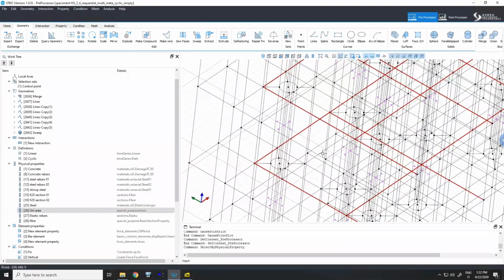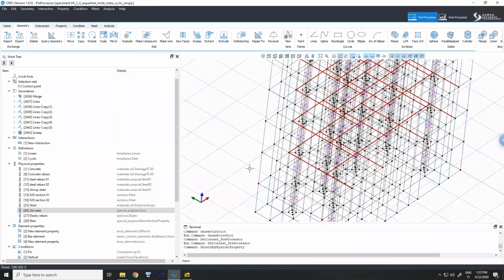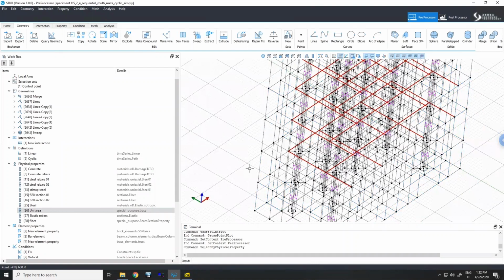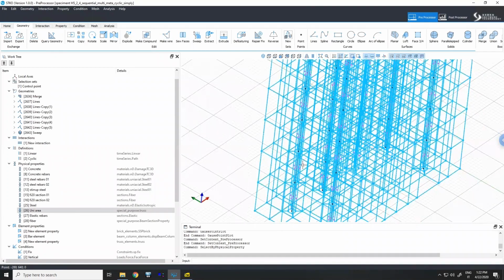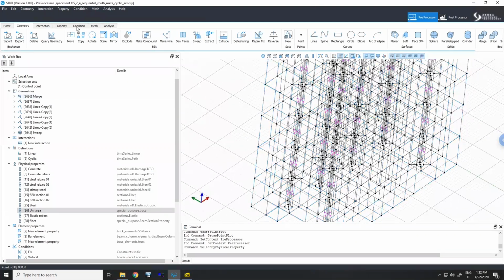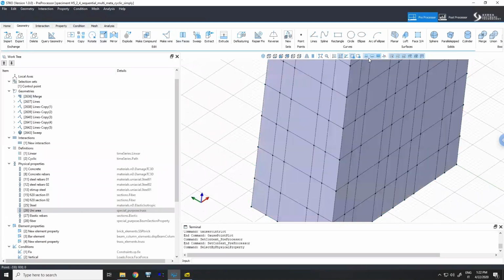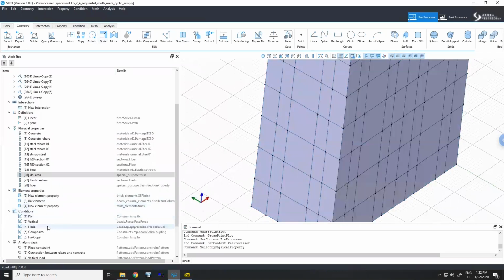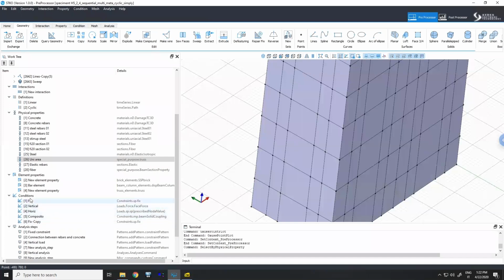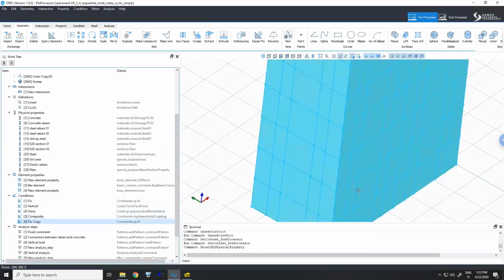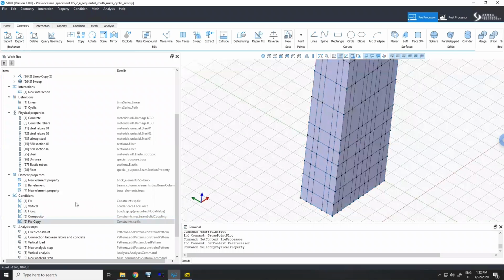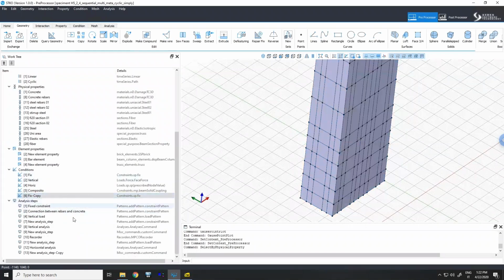Here I can do it only for the trusses, because trusses can have both 3 or 6 degrees of freedom, so it is safe to assign it. Okay, so if we go on, of course, you have a set of boundary conditions here. You have to fix at the base, vertical forces, horizontal imposed displacement on top, solid coupling, and then you also have the symmetry condition, because in this case it was symmetric, so we took advantage of the symmetry condition.